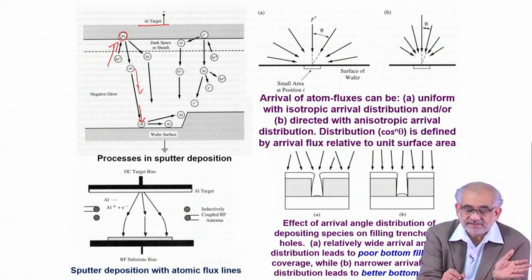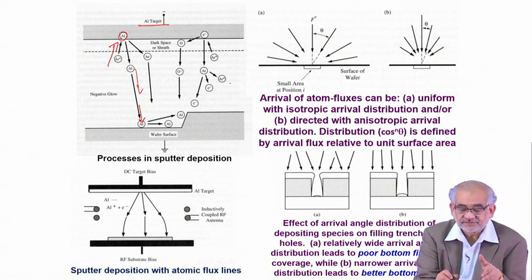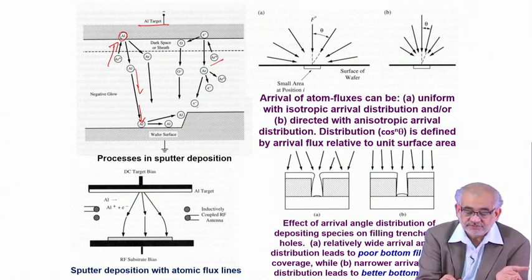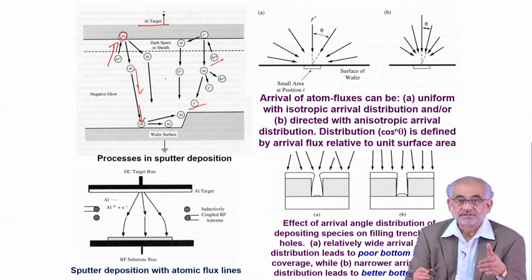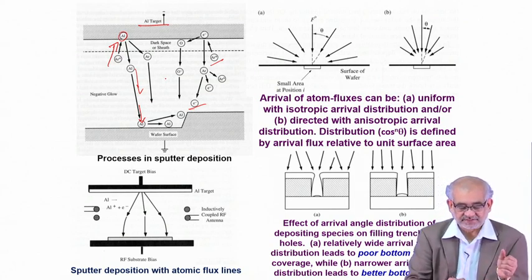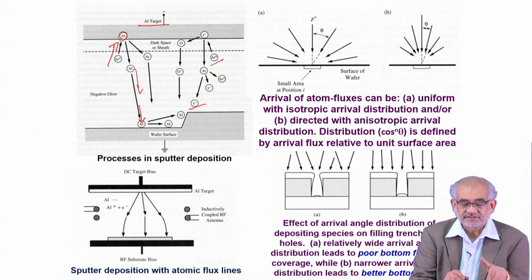But in the process, it can hit the atmosphere inside, or the atoms inside, and since we are dealing with plasma, obviously we have these argon ions, cations, and also electrons. The density of them will vastly control the rate and also the uniformity and the composition with which they arrive. So this can be controlled, like I was saying.